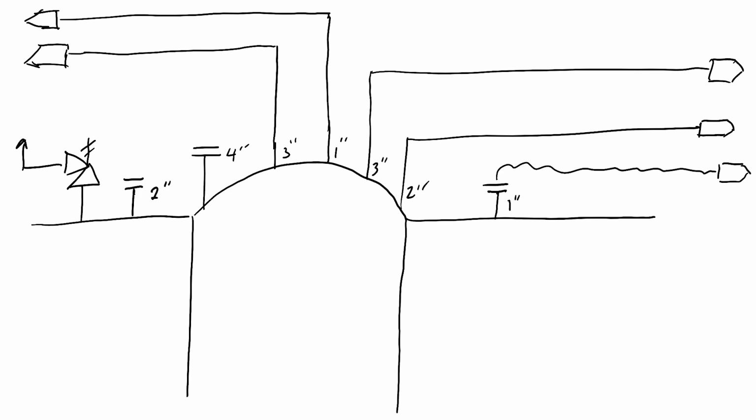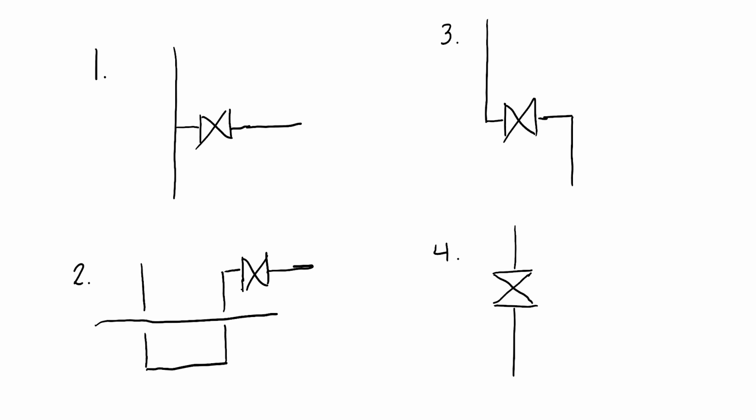That's some tools that you can use, once again, because this is not an isometric sketch. This is just the P&ID, really to make that simplified where everybody understands what's going on. As you can see here in the second one, we have a couple different sketches of basically a valve in the line. So number one, important point there, this is showing the valve on the other side of the T. So this is important to arrangement.